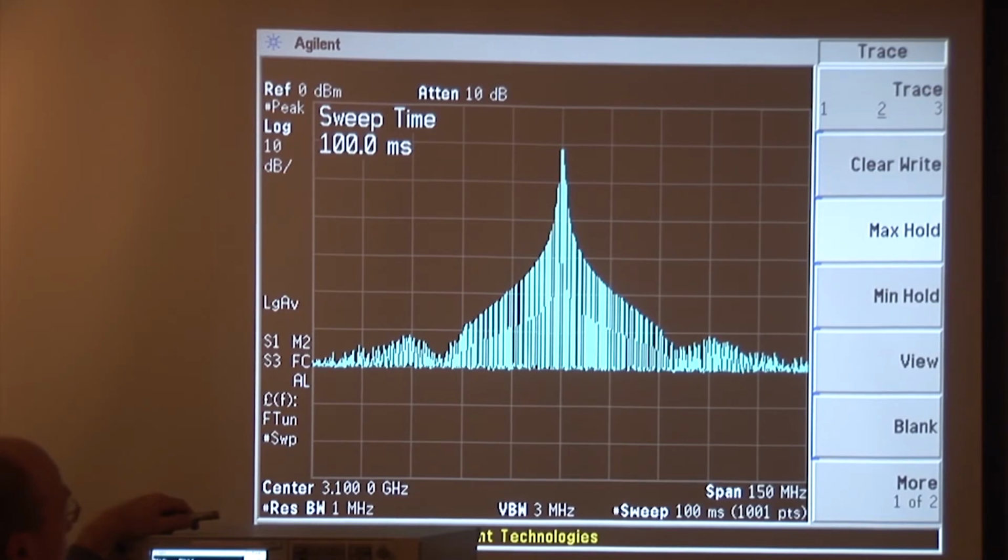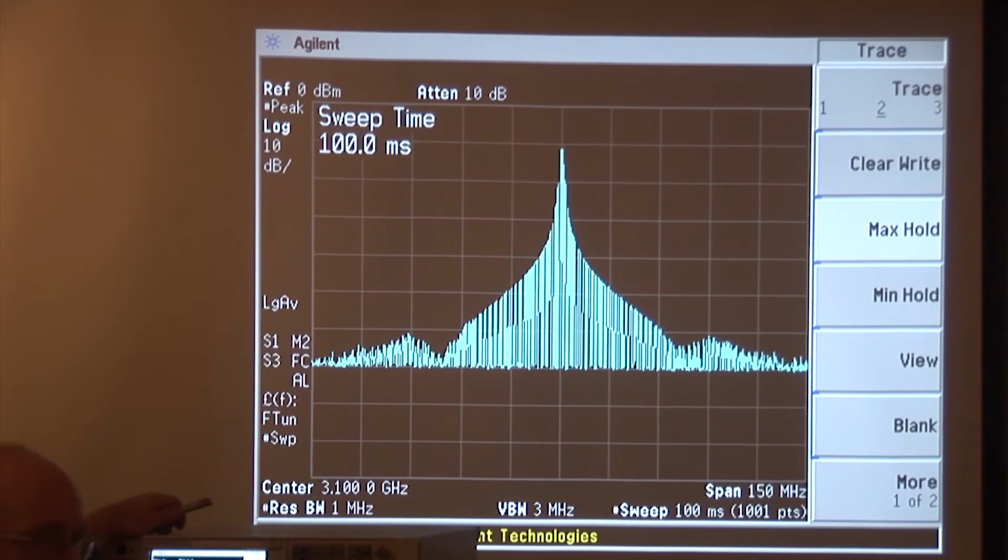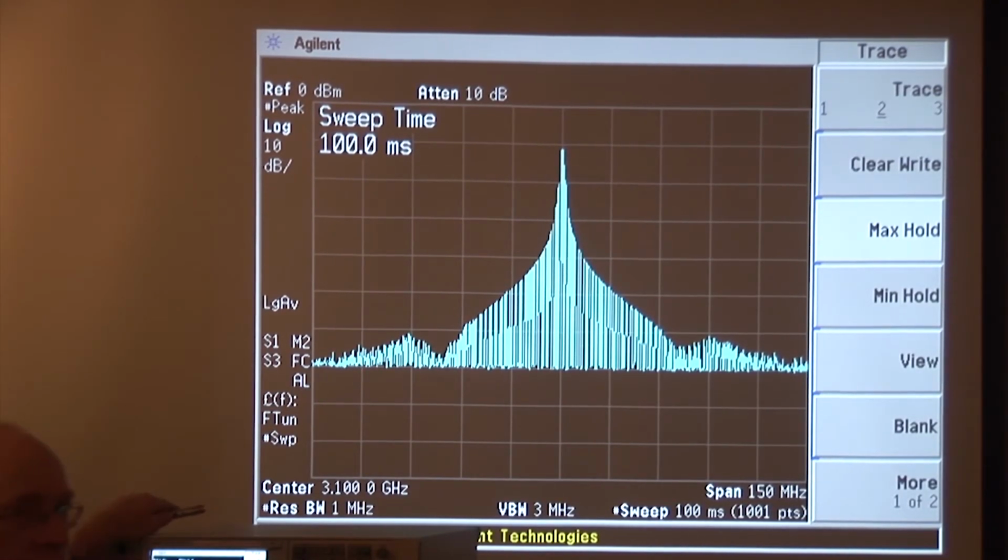So you still get an update, however you won't get the update exactly every 4.5 seconds. You might get an update 3 seconds apart, then another update 3.5, then an update at 4, then 4.5, then back to 3, then 4, then 4.5. It'll vary back and forth a little bit. But they won't let it go 30 seconds without looking in our direction, because that would leave them blind to something that's happening in that direction. But if it is a phased array, you won't get the deterministic update that you get with a rotating array. Instead, you'll get a little more random update. But you'll still have a delta t within which it will come back to update you.